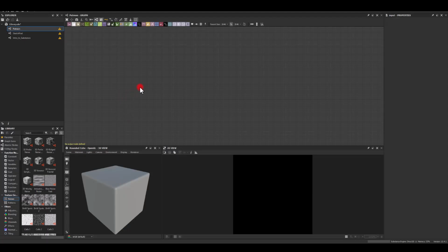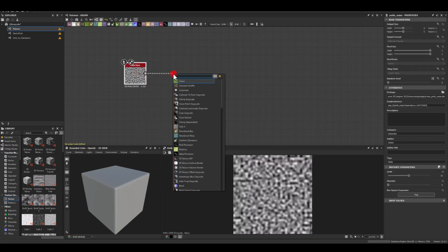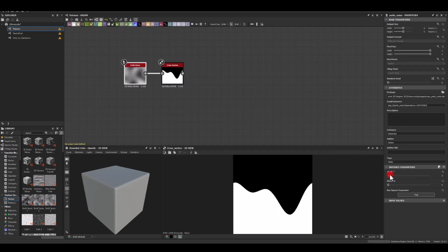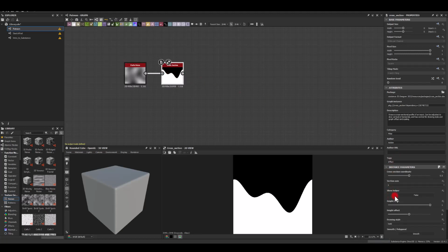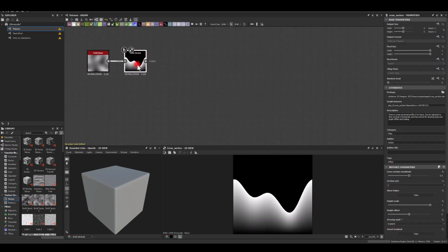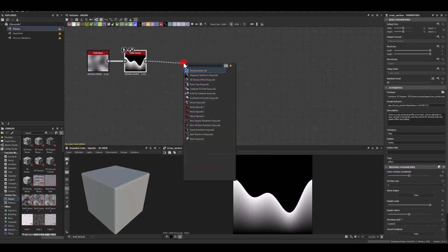So that texture is gonna be super simple. I just want to have 3 waves, so I can apply it to my UVs and onto my mesh. So I'm gonna start with perlin noise because I wanna isolate the trail. So I'm gonna use cross section to do that. I'm gonna scale down my perlin noise so I could get something like this, but I want this to be a bit more flat. Okay, could be maybe something like that. For the cross section, I'm gonna check the gradient mirrored, or maybe just a gradient, and I think just the gradient should do.